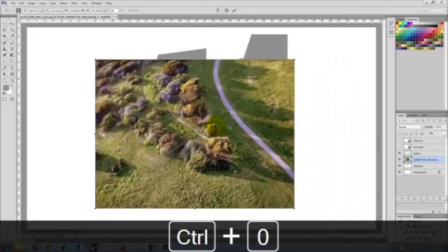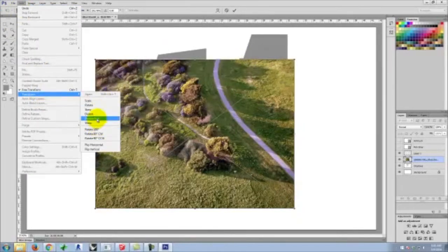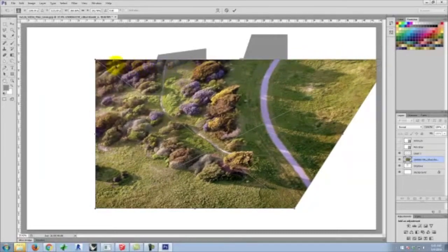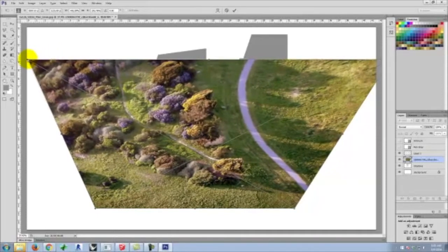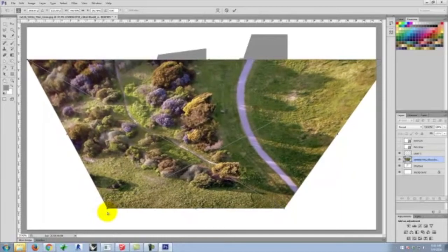Okay. So if I look at this particular image, I'm looking kind of down at it, and the receding lines would be going off this way. So I'm going to go into Edit, Transform, Skew. And I'm going to take each of these sides out like this to flatten off the image. And so I've taken away the perspective view of this, and I've distorted it down so that it's more of a top view. Does that kind of make sense for how I tweak that?